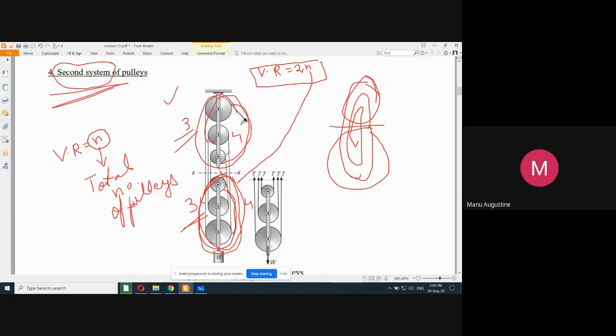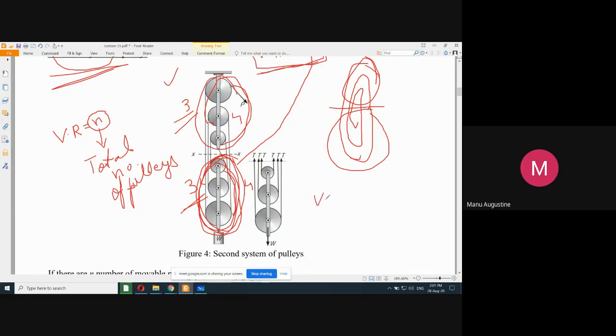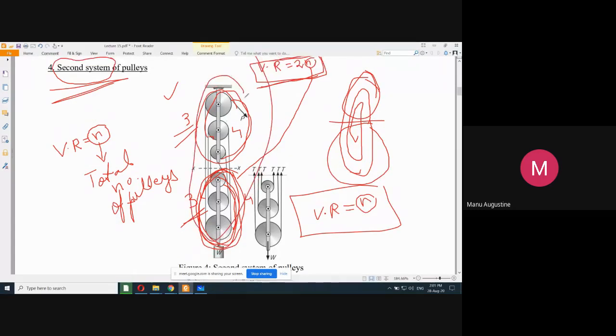तो ये तो एक केस लिया है अपन ने जिसमें 3-3 पुल्ली थे। अब 4-4 पुल्ली, 5-5 पुल्ली, 10-10 पुल्ली, कितनी जगह आपके पास अवेलेबल है, उस हिसाब से बड़ा सिस्टम भी बना सकते हो। So this is a general expression that if I make a set with n number of pulleys, then the velocity ratio becomes 2n. और एक दूसरा मेथड क्या है वेलोसिटी रेशियो का, इसी के लिए वेलोसिटी रेशियो is simply written as n। और इस केस में n is the number of all pulleys in the system।